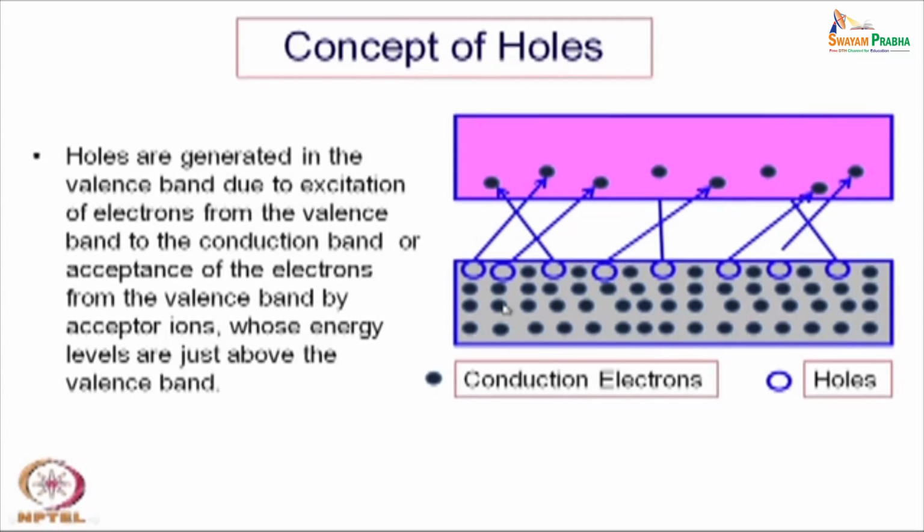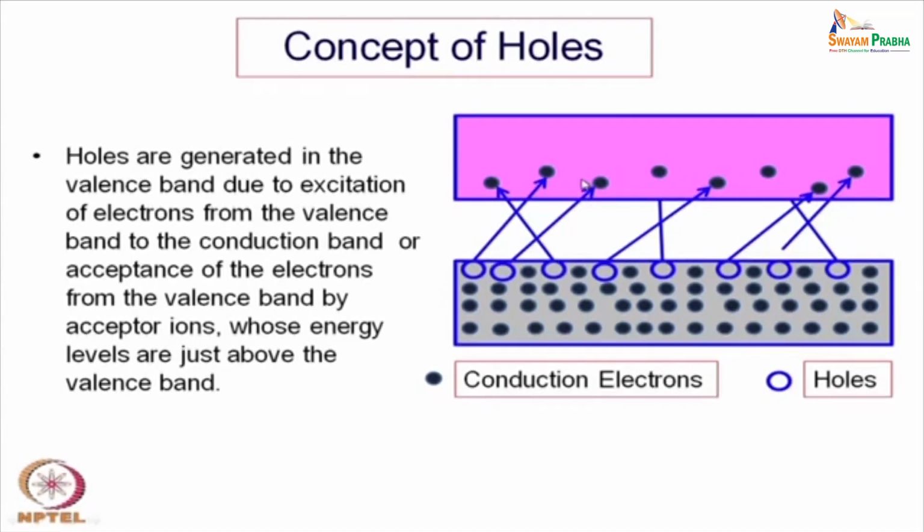By adding certain impurities of two different kinds, one can either accept electrons, which are called acceptors, and create holes in the valency band. The other variety is to donate electrons to the conduction band, and then of course, there is no question of a hole there. The corresponding hole will not be created, because a second element has come into the process and there is no hole created.